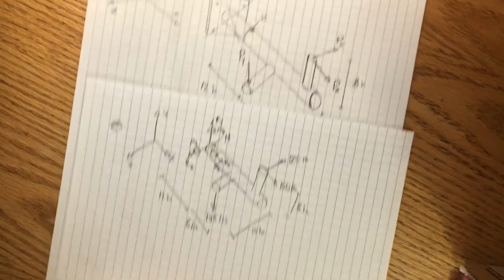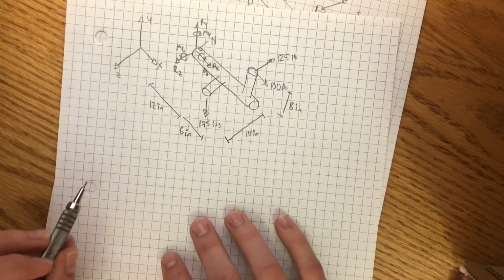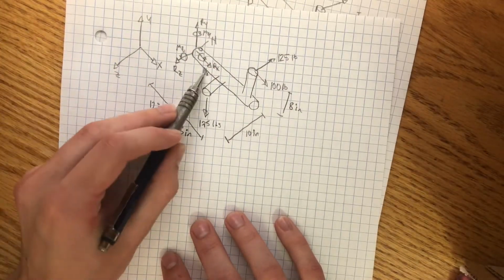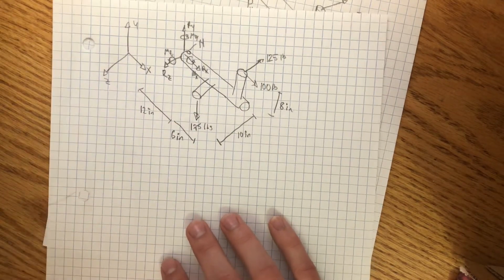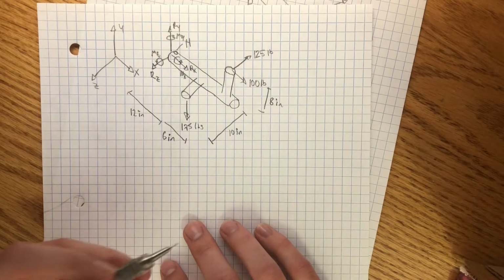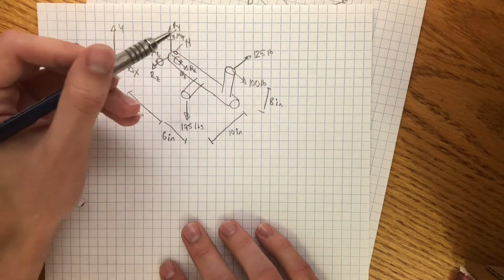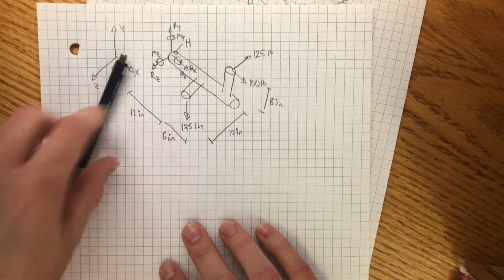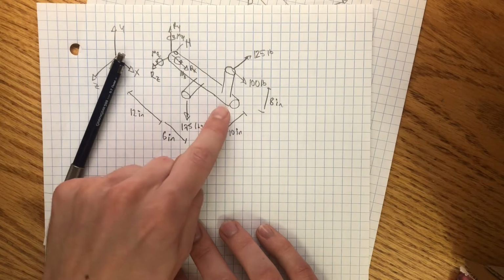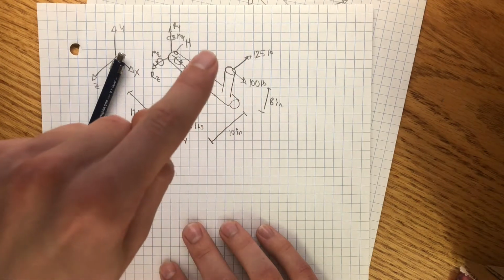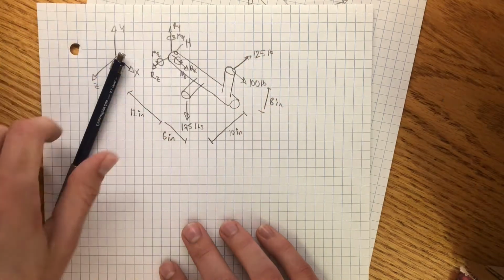And now what we're going to do is, we can pretty easily find what the reaction forces are based off these forces. But moments can be a little bit trickier because you need to analyze a lot about the plane. You know, this force would create a moment about the y-axis that twisted it like that, but then it's also elevated from the origin, so it actually also creates a moment about the x-axis and stuff like that.